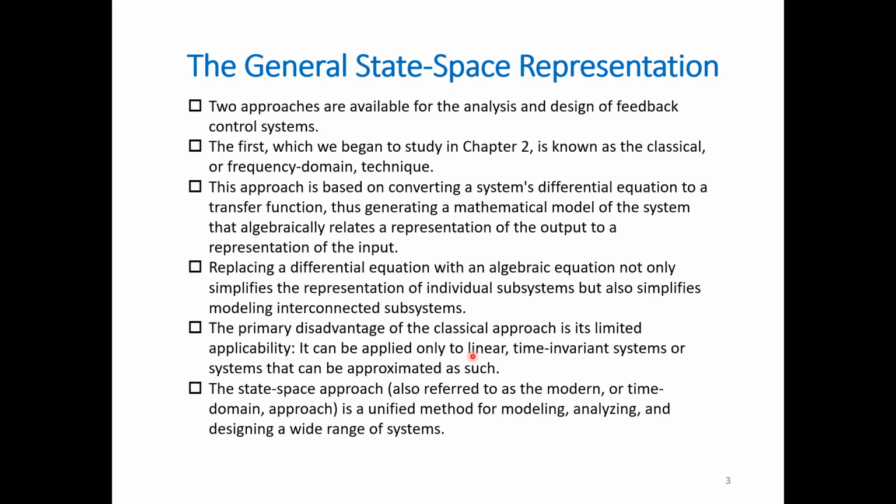We studied the frequency domain technique in chapter 2. The approach is based on converting a system's differential equation to a transfer function, thus generating a mathematical model of the system that algebraically relates a representation of the output to a representation of the input.